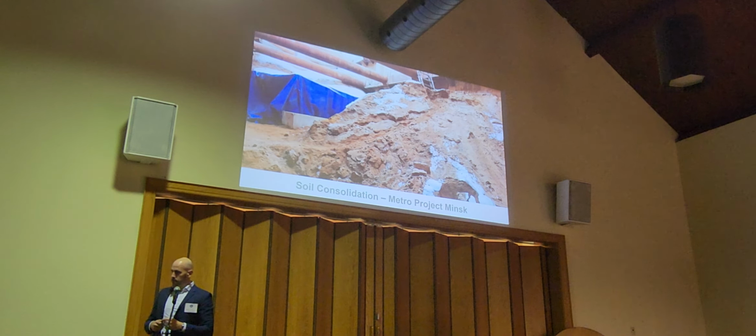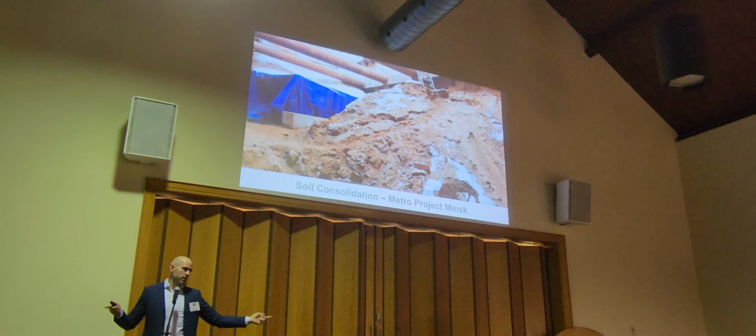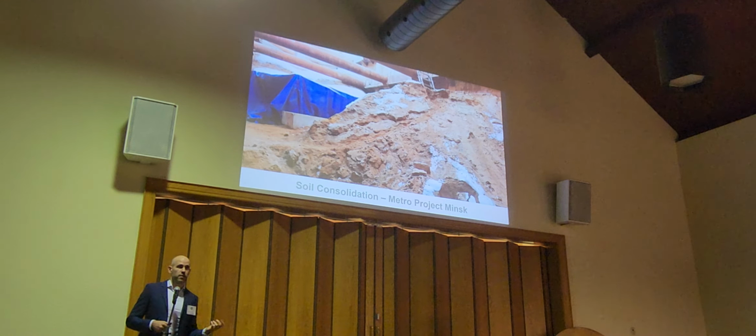So the task which they raised was, okay, I want one injection point which reached 2 meters diameter in my porous soil here, and I want to create something where I can excavate in. Because if I have too much strength, or if I use polyurethane resins, for example, I will not excavate. So it was also a question of what type of material to use.